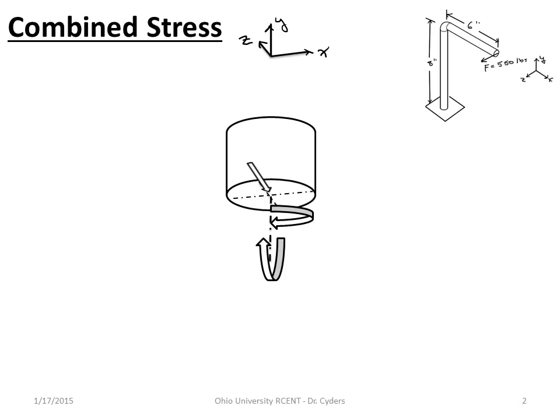To reiterate, just because this is a very important point, we can see that the transverse shear, if you think intuitively again, my transverse shear across this cross section is going to be constant. And across this cross section, it's also going to be constant at a 550 pound reaction. That means that my bending moment here, in this case, that would be about y.